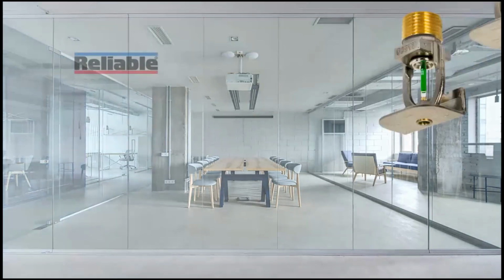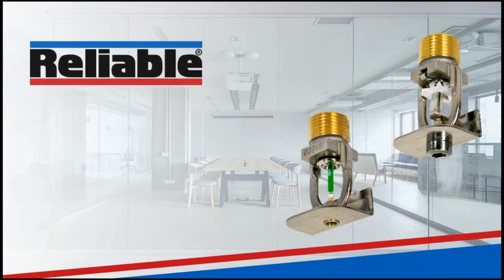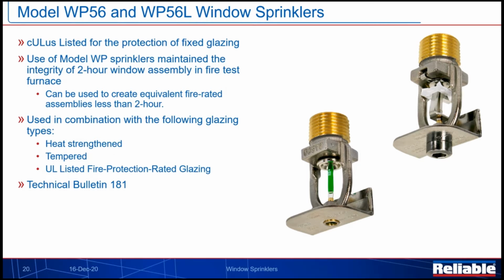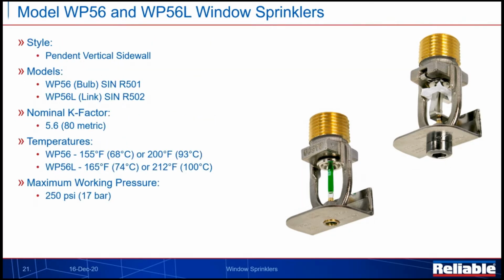So what we get after doing that is our Model WP window sprinkler series. These were introduced earlier this calendar year, and these are UL listed for protection of fixed glazing products. They have a demonstrated capability of 2-hour fire-rated equivalency through that testing at UL. And we have 3 glazing types that they're meant to be used with: heat strengthened, tempered, and UL listed fire protection rated glazing material. Full details about this product can be found in Bulletin 181 on our website.